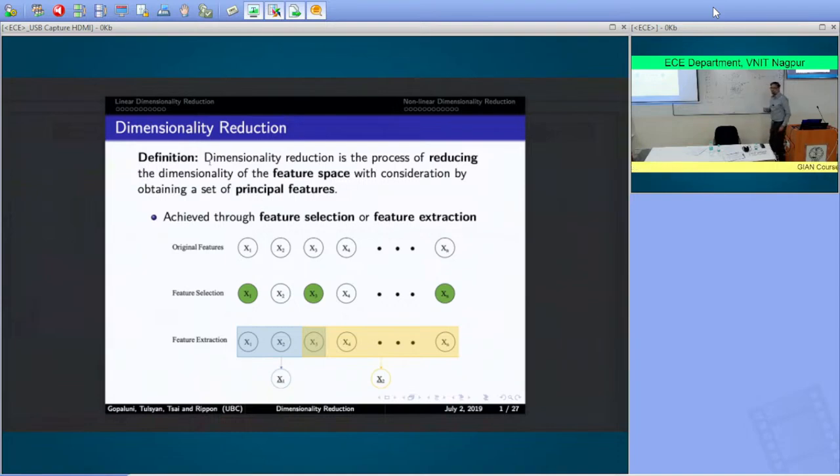If there is something that breaks down with your process, the underlying system dynamics, then you will notice that these data points move to a different location in the lower dimensional plot. Okay, so that tells you maybe something has gone wrong with your process. Now, if you're trying to monitor these variables in the original space, where you probably have 5 or 10 different dimensions, it's not possible, right? So if you have 10 dimensions, you cannot visualize 10 dimensions on a piece of paper. But if you reduce the number of dimensions, it's much easier to visualize. Okay. That's one reason